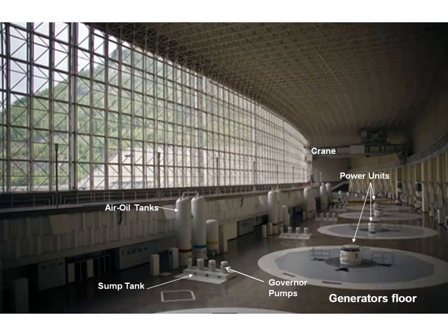The problem is that one of the turbines that was spinning started experiencing cavitation. And so these little air bubbles were forming. And the cavitation can, as the little vapor bubble collapses, send a shock wave through the water, and it can cause pitting or erosion of the steel in the turbine blade. And so it started wobbling. The turbine started wobbling, and people think that its vibrations and its imbalance is probably because there was pitting and cavitation damage of the impeller that was spinning around.